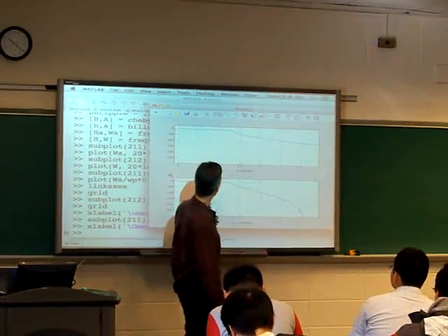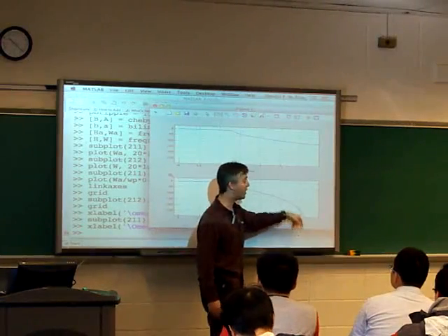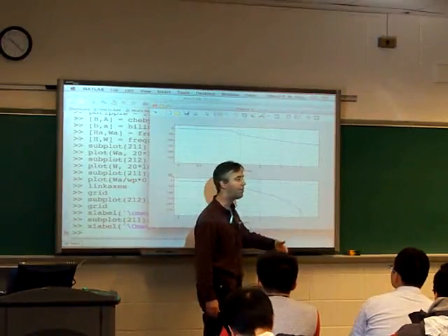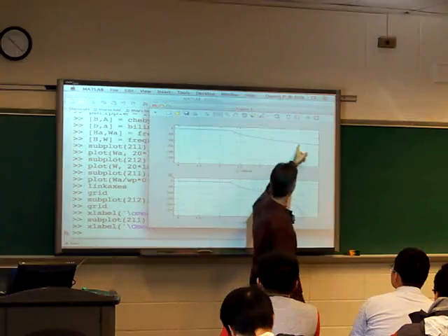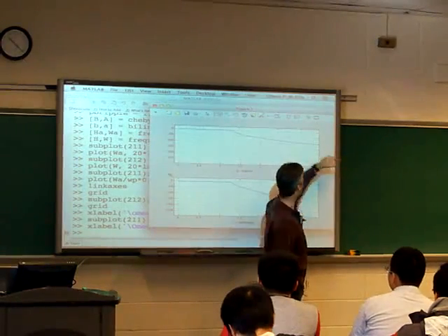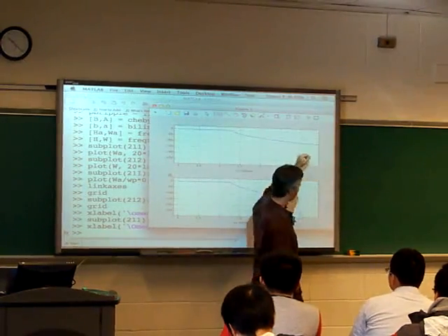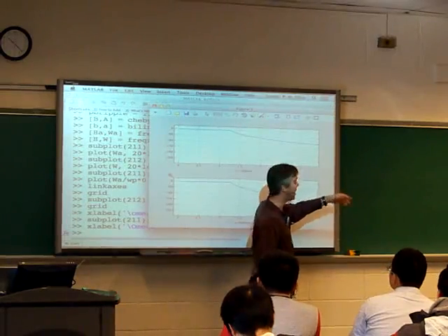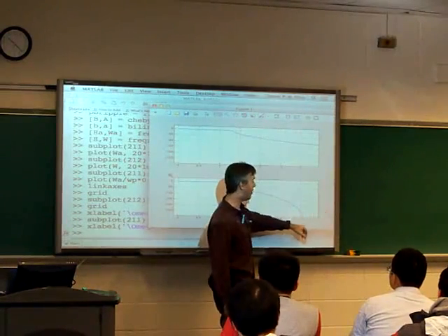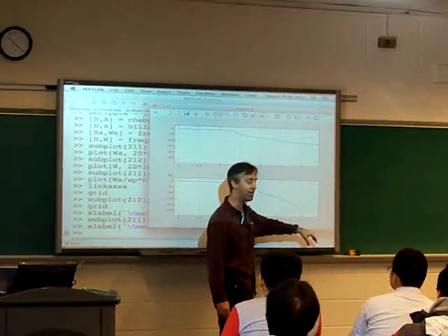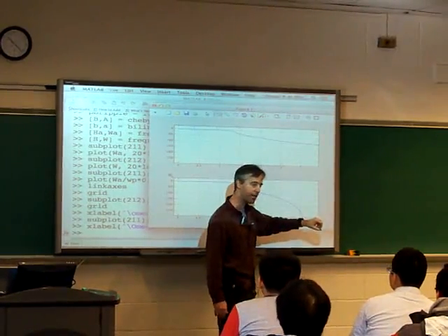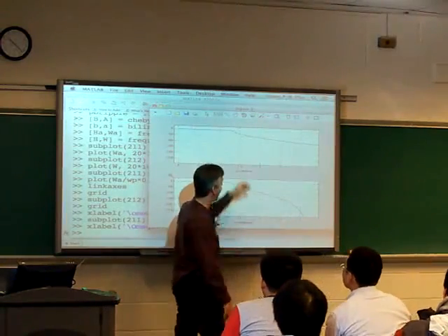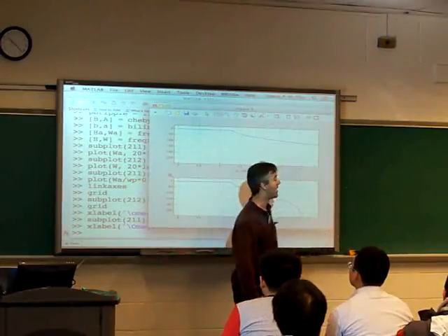And what happens for this Chebyshev 1 filter is that the gain actually goes to 0 at omega equals pi, which is to say that this is monotonically decaying, and it gets shallower and shallower as time goes on. If you go to infinity in continuous time, the gain of this low-pass filter is 0. Of course, you'd never get there. But here, in discrete time, we actually do see that value at infinity. And we saw there were a bunch of zeros at z equal -1, corresponding to what happened when you got to the end of frequency on this plot.